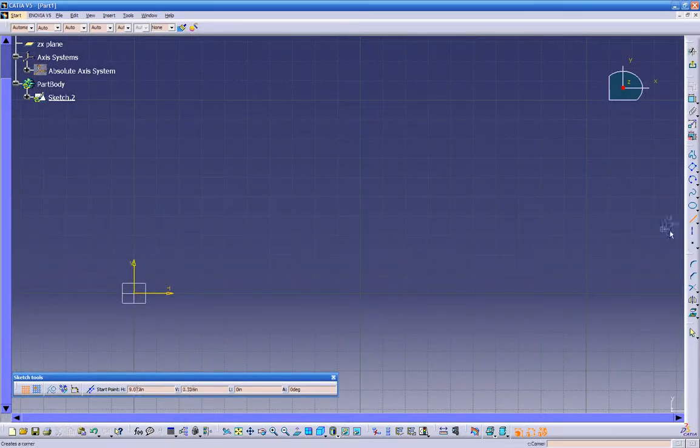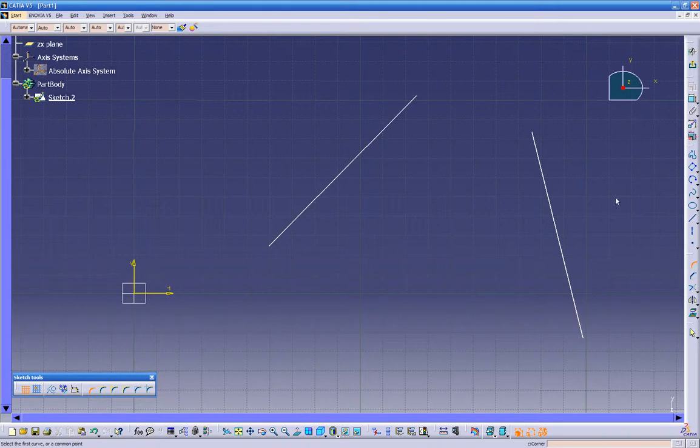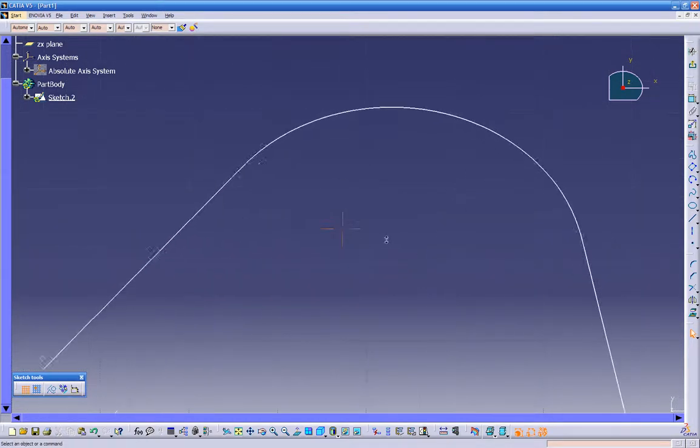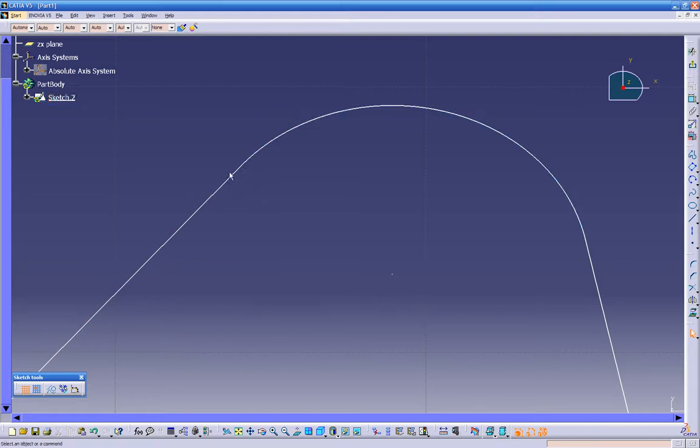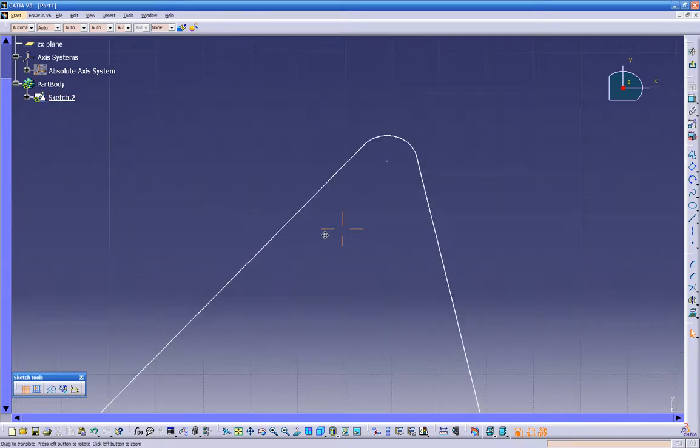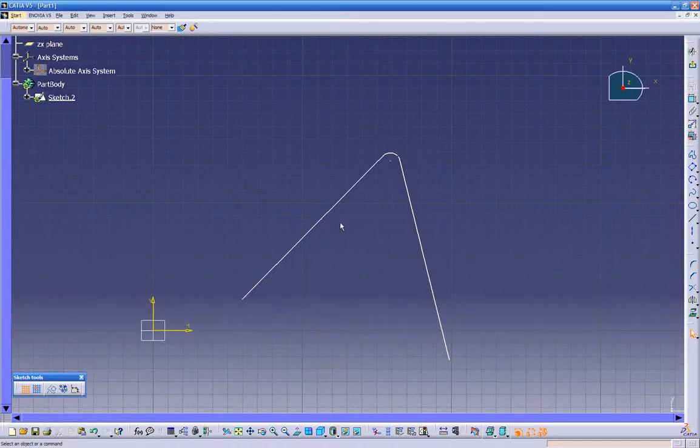So pretty much, let's try one more time. Create another line, and let's click escape, get out of here. Let's go to corner radius. Let's pick line number 1, line number 2, and before we snap it into place, let's click the tab key, and let's type in the dimension over here, 1/4 inch. And let's see, as we zoom in here, we can tell we have a perfect tangency between this line and this arc. So that looks pretty good. I like this option better.